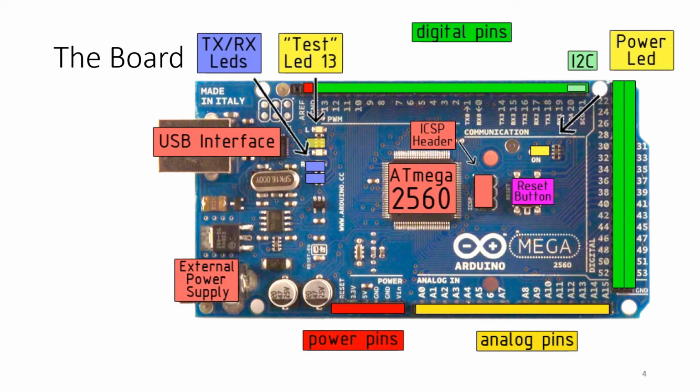The Arduino Mega has a resettable polyfuse that protects your computer's USB port from short circuit and overcurrent. Although most computers provide their own internal protection for the devices, the fuse provides an external layer of protection. If more than 500 milliamp is applied to the USB port, the fuse will automatically break the connection until the short circuit or overcurrent is removed.